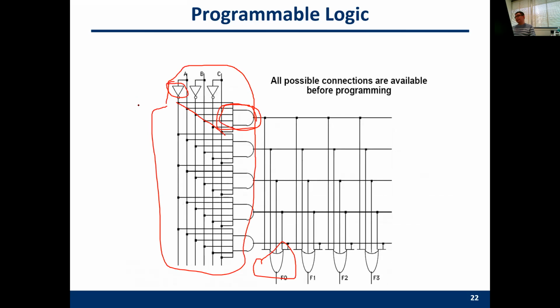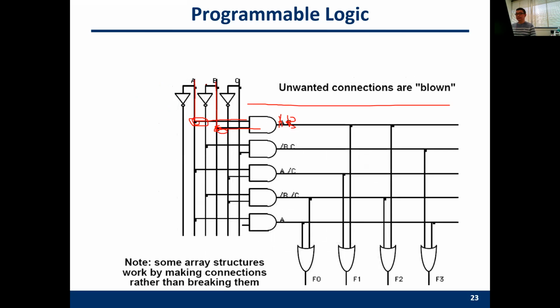But in this figure, this is a full functional decoder, and you have all these connections. But you can control this dynamically. So, for example, for this row, if you want to have B bar and C, you keep this part closed and keep this part closed. Based on the value of each row here, you can adjust the switch in this part.